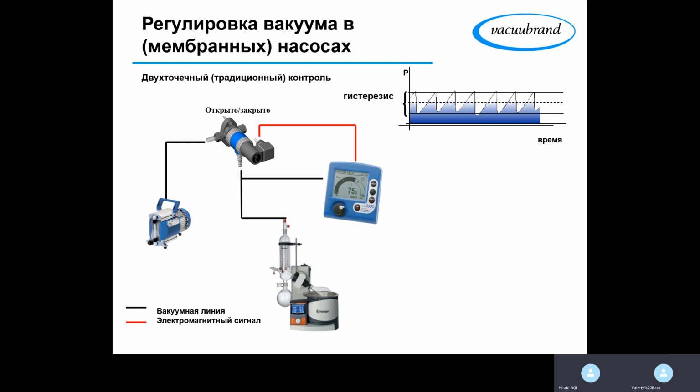Okay. I'm sorry, can I ask? You said the height of the spiral should be 2/3 loaded? Yes, we call it 2/3 loaded. So when we start to boil, how do we define that the condenser works properly? If the condensate is higher than 2/3 of the height of the spiral, then we are overloading the condenser. Now I got it. Yes.